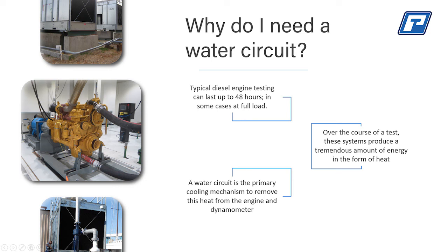I think the biggest thing is what people have to understand is in a failure mode, if you lose water when you're operating a water brake, basically what happens is you have no load on your engine. If you lose water when you are cooling an eddy, you'll burn up the eddy because the water is the thing that's carrying away the heat from the eddy that's creating the load. Okay, great, thanks.